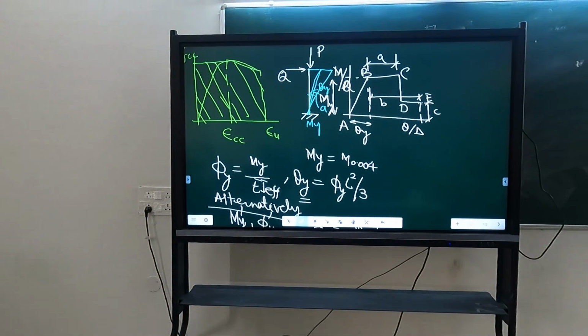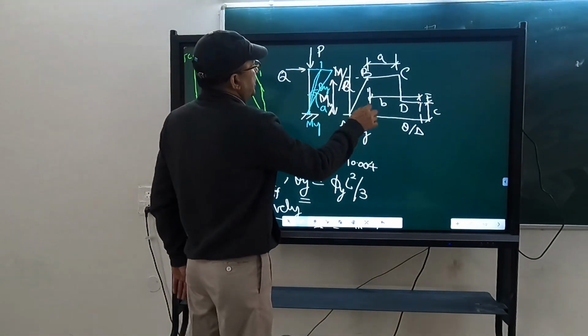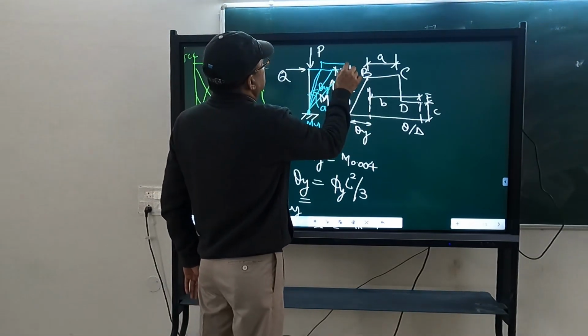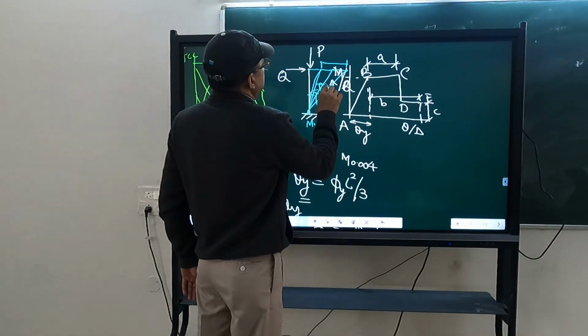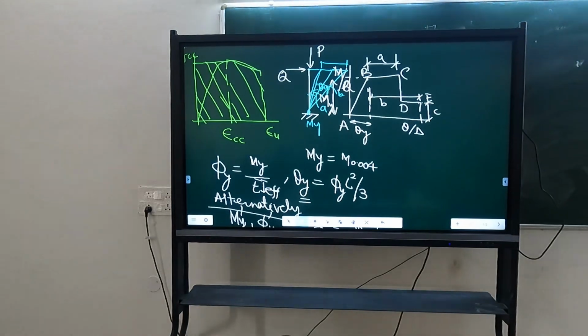And sir, for B also, we are measuring from that new chord where yielding is. B also we are measuring from here, from the same point from where we are measuring A. So B is also measured from here. So this A value, cantilever B and this, they would be the same. So what is A? A is M versus theta, so moment versus rotation.